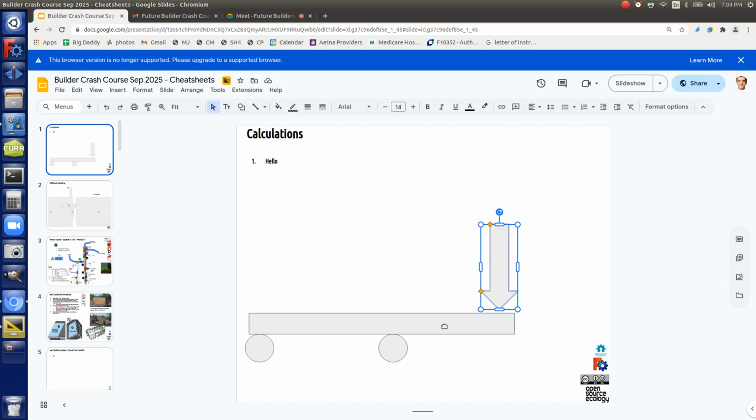You can calculate it and you can use FreeCAD with finite element analysis, but the practical consideration here is, no, you're not going to do that, and you've got different materials, so you just ask Google, what's the bending, the deflection? It's called deflection. So Google up a deflection calculator online, and you say, what is the deflection of a 2-inch steel shaft supported 4 feet away from the deflection point? And it'll tell you.